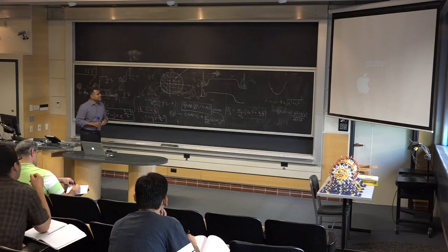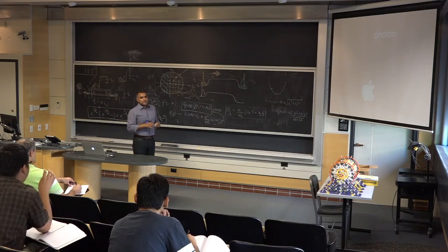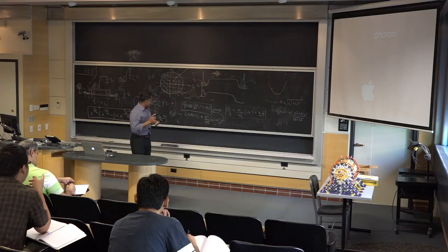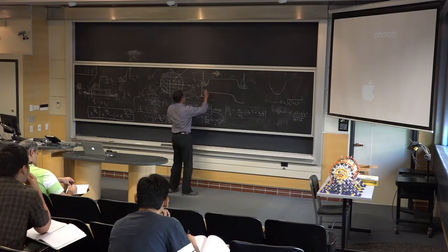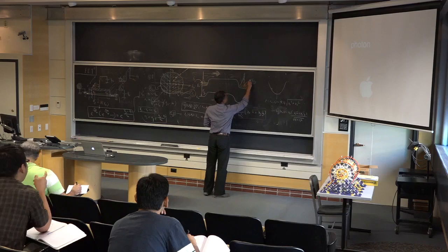Yeah. This is based on the conduction band of the source and the drain, right? Not the conduction band near the gate part, right? That's right. So the Fermi levels are indeed the source Fermi level and the drain Fermi level. I mean the conduction band.